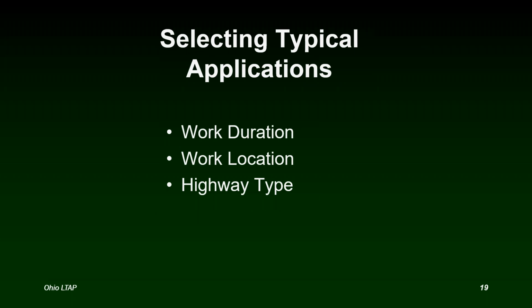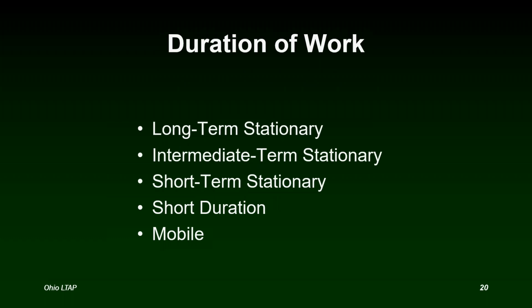Also, some other things that affect your work zone design is the work duration. How long are you going to be out there working? Is it just for 15 minutes or something, or is it going to be 3 days or more? That has an effect on your work zone design. So does the location of your road within the right of way, and also the roadway type. Is it a 2-lane road, a 3-lane road? There's a lot of 3-lane roads these days with a 2-way center turn lane in the middle, or maybe it's a 5 or 6-lane road, or maybe it's a freeway. All of these have an impact on the design of your work zone.